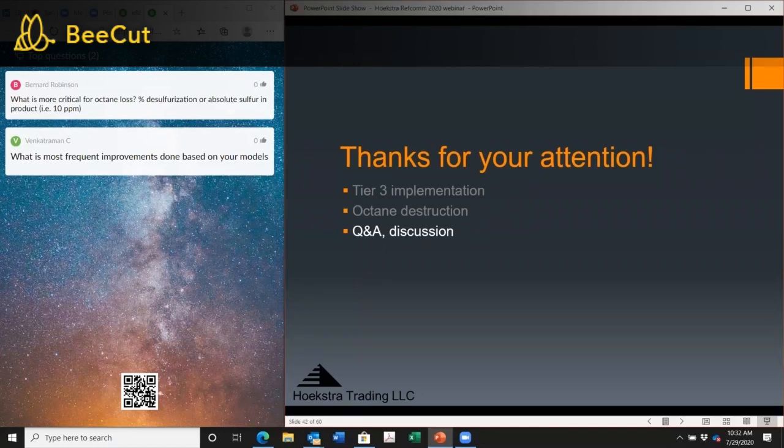So I don't know whether this question was suggesting that cat feed hydrotreaters are good, but I believe they are. And I think the big weakness in our infrastructure today for making Tier 3 gasoline profitably is that we have many refineries that don't have a cat feed hydrotreater and still want to be able to vary their crude slates and want flexibility. And for those refineries, they're going to have a much more constrained situation with 10 ppm than with 30.